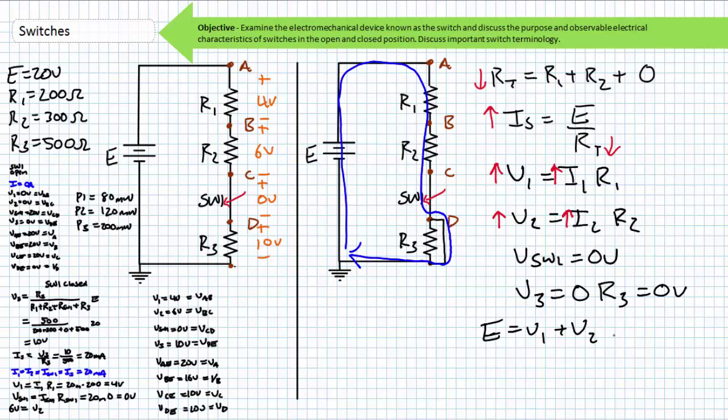This could be a potentially dangerous situation if R3 was an essential current controlling element, keeping current below a manageable limit. Additionally, with a shorted R3, we've effectively created a low side switching arrangement. Finally, with increased current draw and voltage drop by R1 and R2, the power dissipated by these remaining resistive elements sharply increases. Now that we've briefly discussed the expected results of a shorted component in sufficiently general terms, just put some numbers in there.